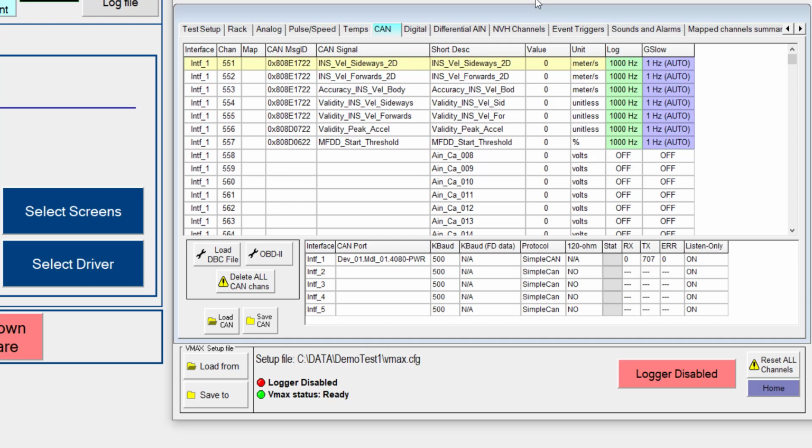Generally speaking, your OBD2 protocol for some of the basic type of signals that should be available on most vehicles is accessible. However, using simple CAN protocol with a DBC file may not be functional until that architecture has been either unlocked, or there could be some rewiring that's required to go around security devices.